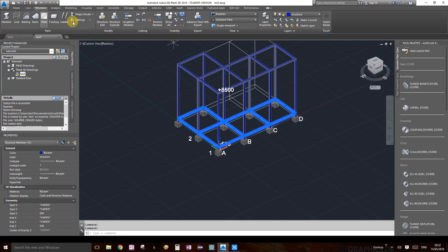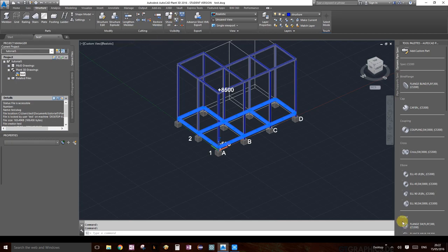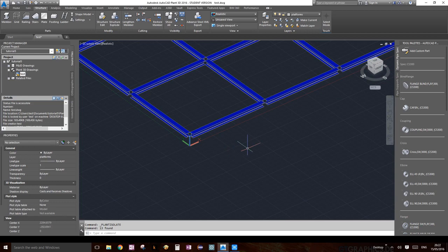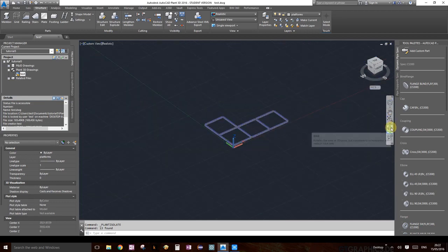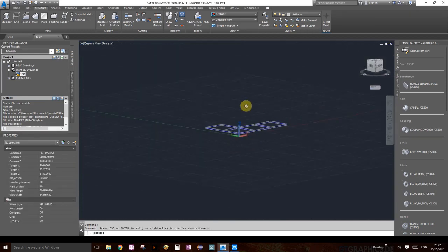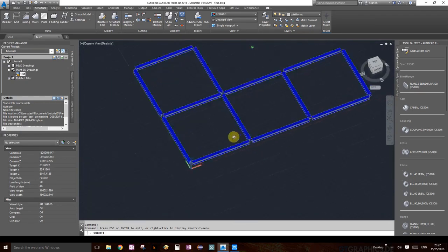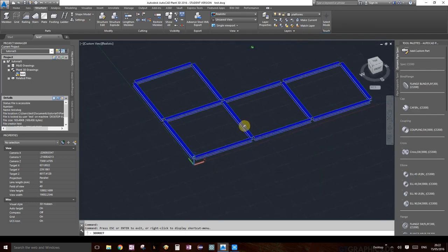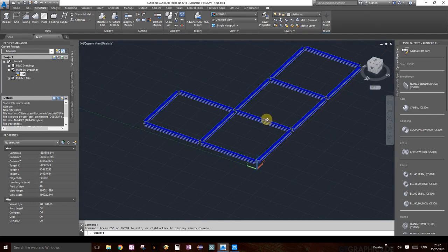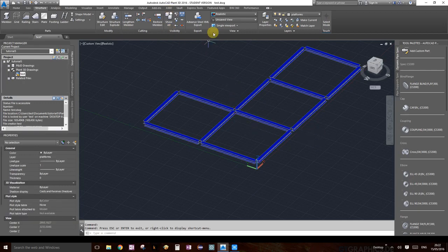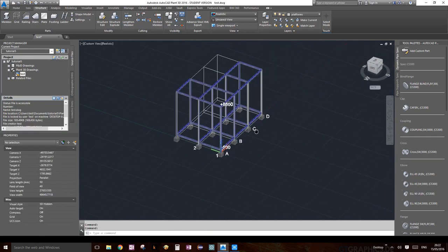And we're gonna go ahead and press on this from structure visibility, this tiny little button there called hide others, and voila, everything is hidden, but it's still there. You can still draw everything and it'll still show up, just not everything else. So you know, there's not a lot of interruptions and viewing clashes and whatnot. And once you've hidden everything, you can easily click on show all and it will pop it back in.